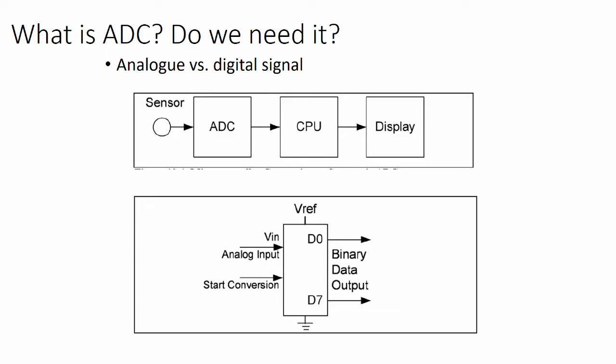What is sensor? Sensor is something that converts the change in signal from one form to another form. For example, temperature sensor PT100, it converts the change in temperature to change in resistance, that in turn can be converted to change in voltage with the help of the bridge circuit, and that in turn could be given to analog to digital converter.